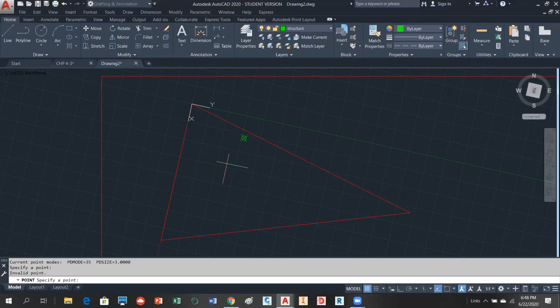Okay. Is that working? Yes. And notice it still says specify point. So now we can do 51. So that has a distance of 33.3 less than 347 degrees, 41 minutes, 23 seconds. Hit enter, and you should see a second point come in. Okay, we getting the idea?